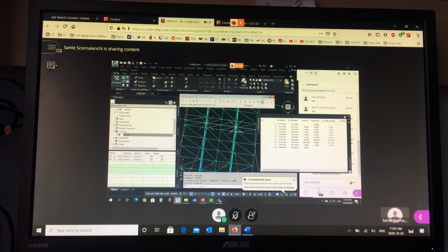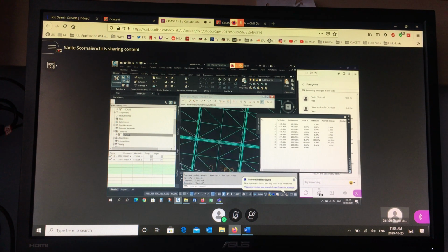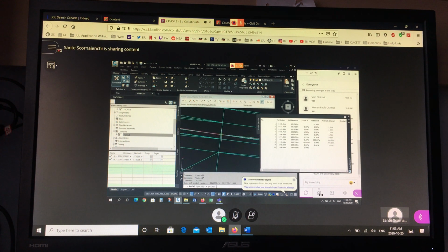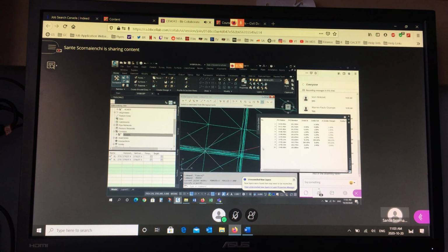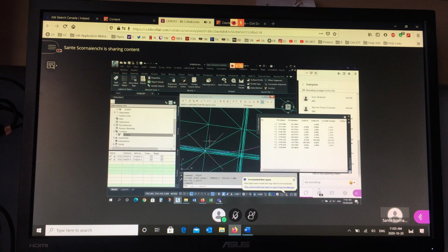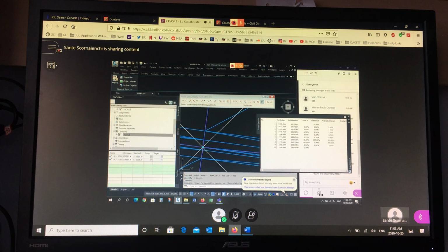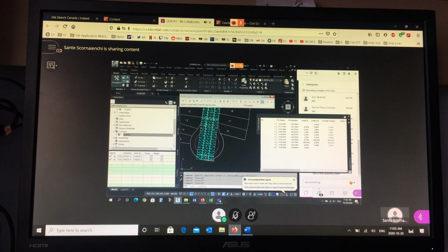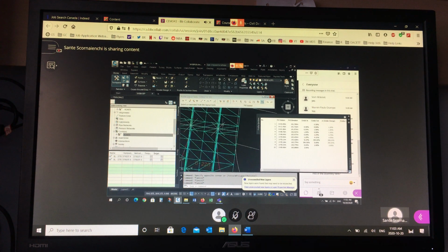This one here. So there's a point there. And then right here, in the gutter, there's an elevation, which is where the center line of the gutter meets the center line of the road. That's where I put my point. So as much as everything is wrong in this entire area, this elevation is what it is now and will be when I'm done, and so is this.